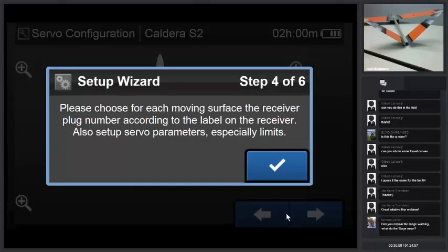There is a short question about the range warning. We are sending 100 frames per second, which means every 10 milliseconds there is a new frame, and the percentage gives the number of frames received in 1 second. So if there are only 30%, 70 frames in 1 second got lost, and 30 frames got received and decoded properly. And that's enough to control the model safely. Yes, 30 frames is still a frame every 30 milliseconds, and you will not recognize this. But if the value drops below, then there usually is something wrong with the antenna configuration.